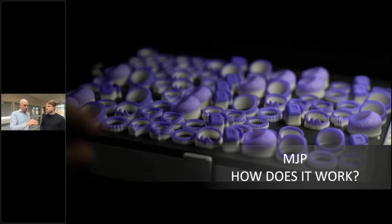In this case, it's a wax material, which is purple. Then you build one layer at a time, and after the part has been printed, you put it in what's called an easy clean system, which melts away the wax. So there's very little hands-on work, and it allows for very complex geometries at the same time.